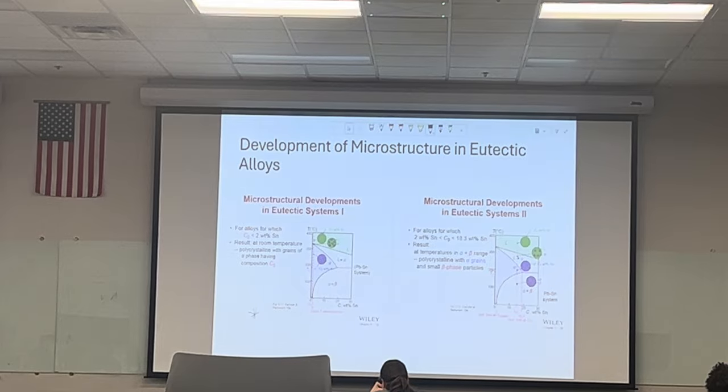So the alloy, if you go up to the 400, it'll start off as completely liquid, and then as you basically start to cool down, you start crossing over the liquidus line. And that's where the solid alpha crystals begin to form, and then that's where you have phase transitions as you continue through the alpha region. And the amount of solid basically increases as the liquid amount is decreasing, as you're making your way down that line.